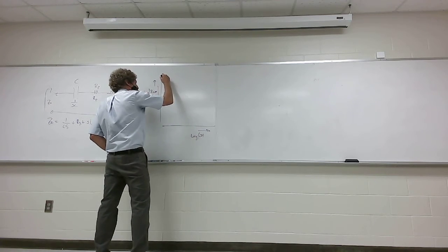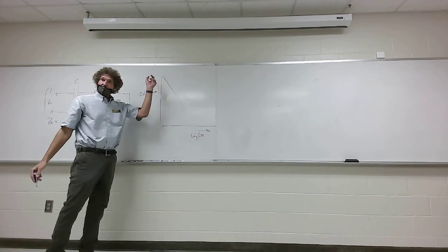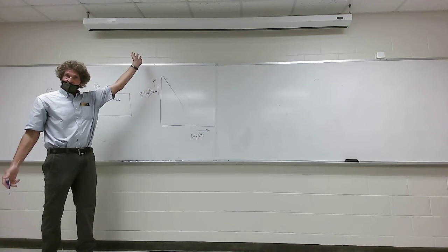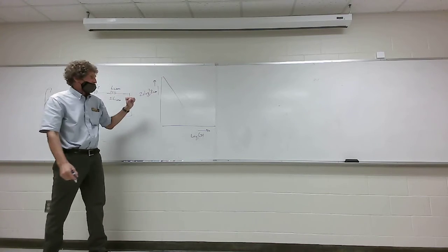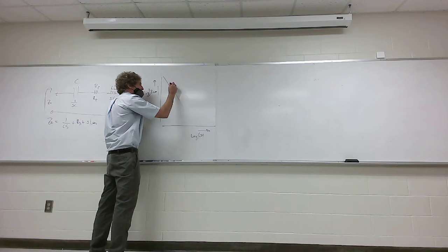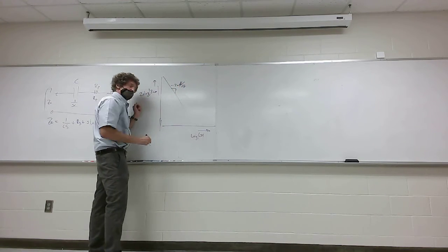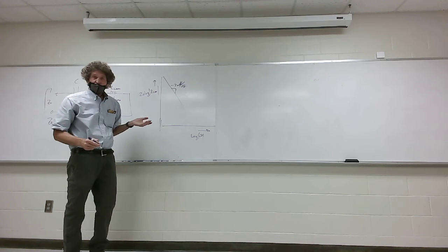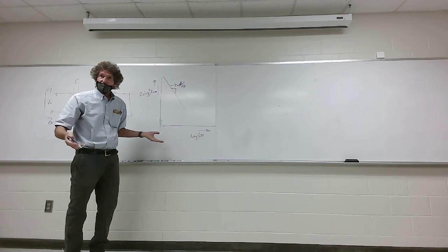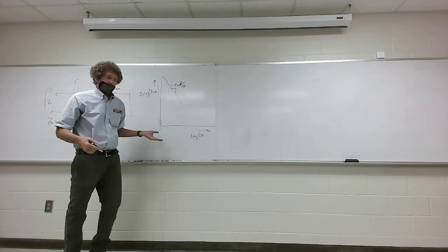You only care about one thing. It's coming in at infinity. You all agree as s goes to 0, this thing's going to infinity. Log of infinity is still infinite. So it's coming in at a rate of minus 20 dB per decade, and it depends where this low frequency is. You can never plot absolute 0 here. So you're going to start at maybe 10 hertz, 100 hertz, something like this.